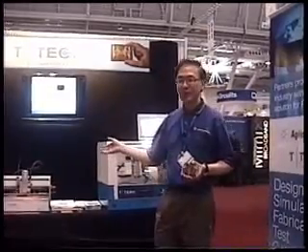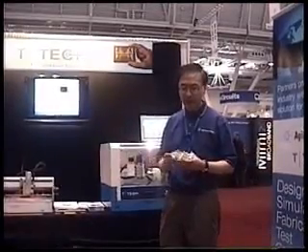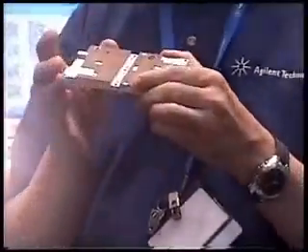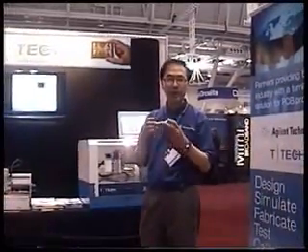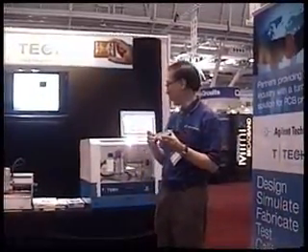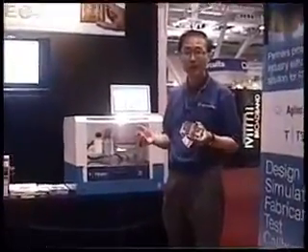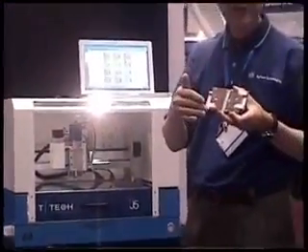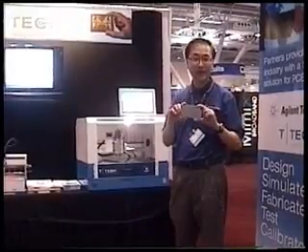So what you saw there was a machine that only fabricated the PCB board or the RF board. But sometimes for power modules like this, where the PCB board is mounted directly on a piece of metal, what you would like to do is the ability to not only make the circuit on a PCB, but also to mill the metal structure around it. And this T-Tech machine also allows you to do that because it has an automatic tool changer, changing to the precision tool to make the PCB structure, and then to a more robust tool for actual milling of the metal housing.